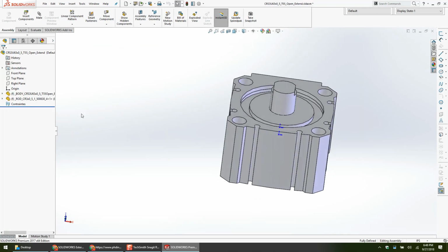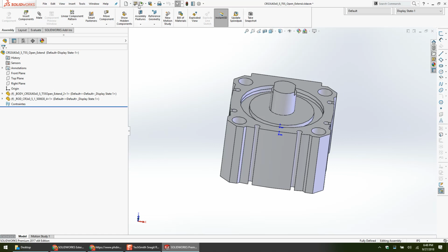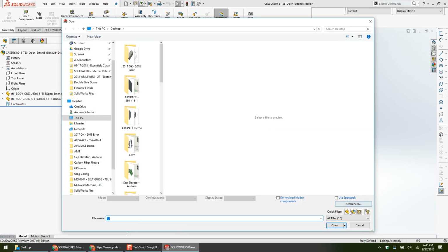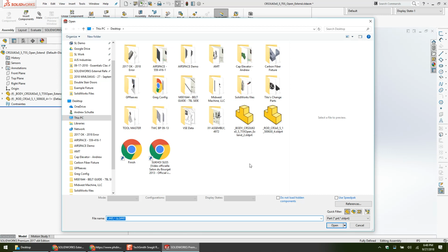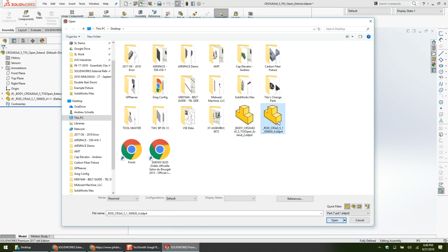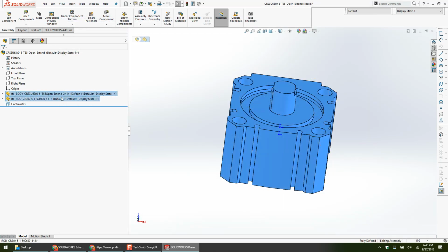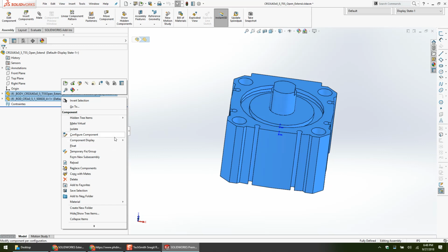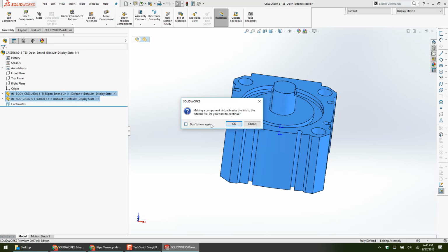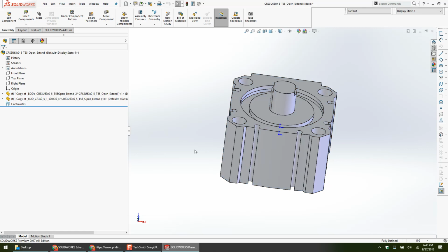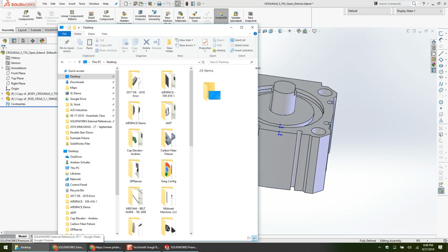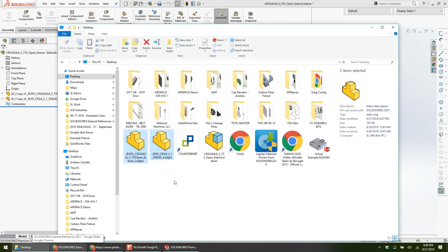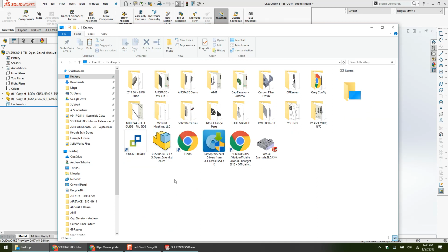Aha! So right now, if we go look at my desktop, I remember what this is now. If we look at my desktop, among all my messy folders and stuff, I see there's 2 files here. If I just right-click on these 2 and select them and right-click and say Make Virtual, shows me an error, yes, I want to make virtual. It breaks the relationship to the files on the desktop. If I go to my desktop now, who thinks the delete key will work? Oh, it worked.